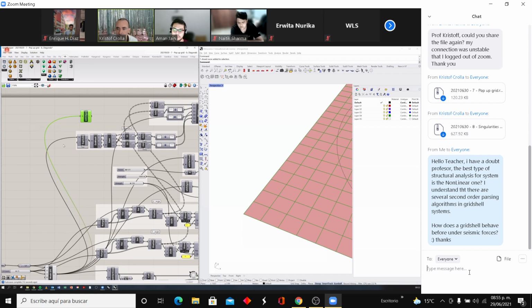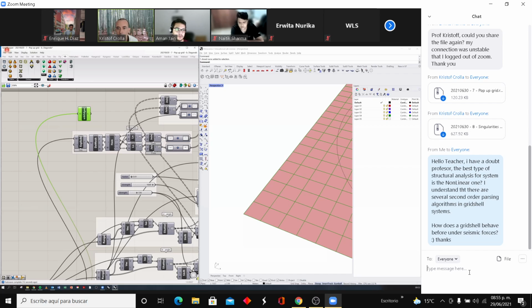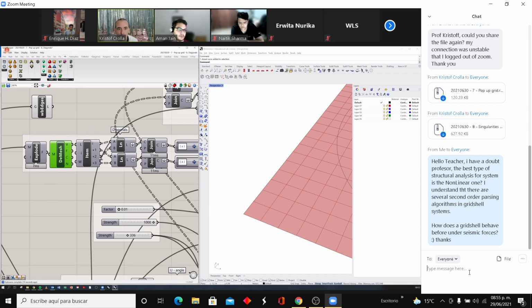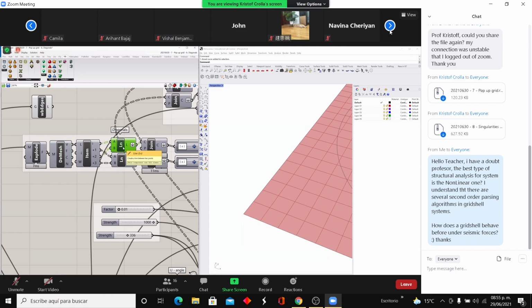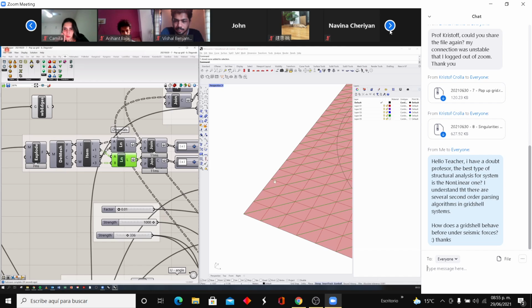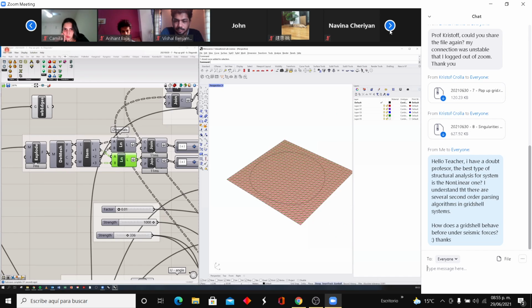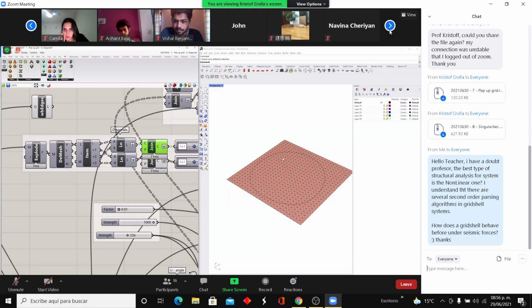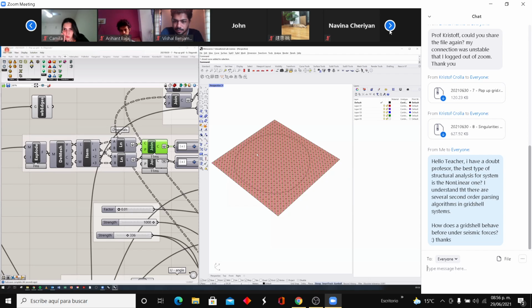Then I extract the vertices from all of them. And then I'm just drawing a line. It's all quads, between either the 0 and the second vertex, or the first and the third vertex. So I'm either drawing all of these lines or all of these lines. And then because these are planar and interconnected, I can just join them to be my curves in the one direction or in the other direction. So that's very straightforward. Those are polylines that use the same vertices as Kangaroo is already using in its calculation, so it doesn't add any calculation time to the Kangaroo algorithm to find a solution.